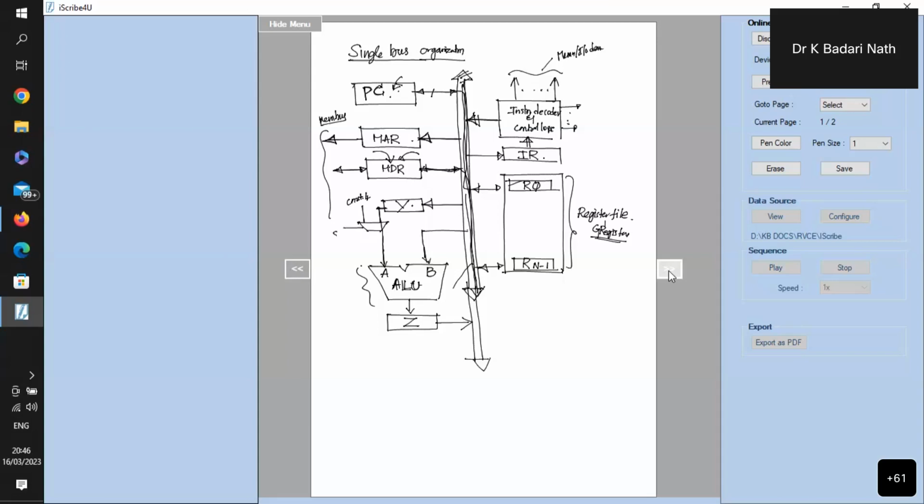There is a select line: if we select 4, the 4 is selected and given to the ALU; if we select Y, let's say first is 0, other is 1, then Y goes to the ALU. That means a 2-to-1 multiplexer is used to select either 4 or Y and give it to the ALU.